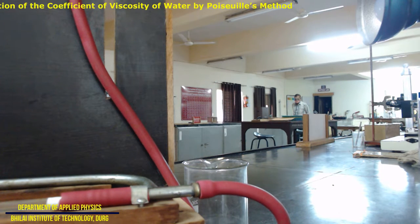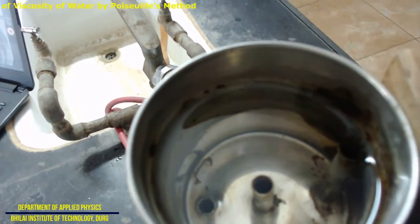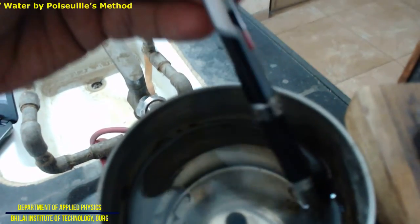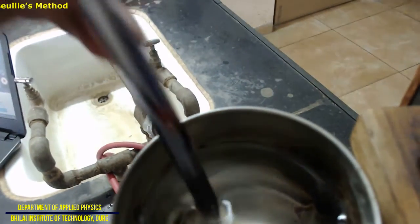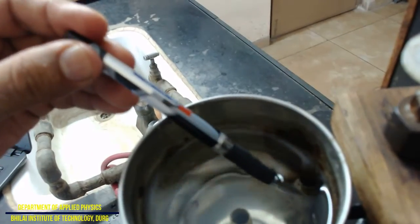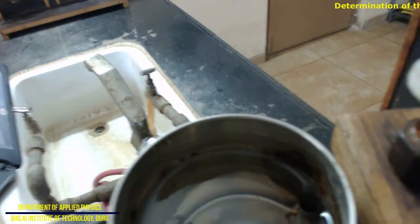So before going further, let us see what a constant level tank is. In this tank you can see three inlets: first inlet, second inlet, and this is the third inlet. The first inlet, the lowermost inlet, is the input, the middle inlet is the output, and the last one is the overflow. So when we keep the tap on, even if the water comes in regularly, the height of the water cannot rise above this. So this is a constant level tank.